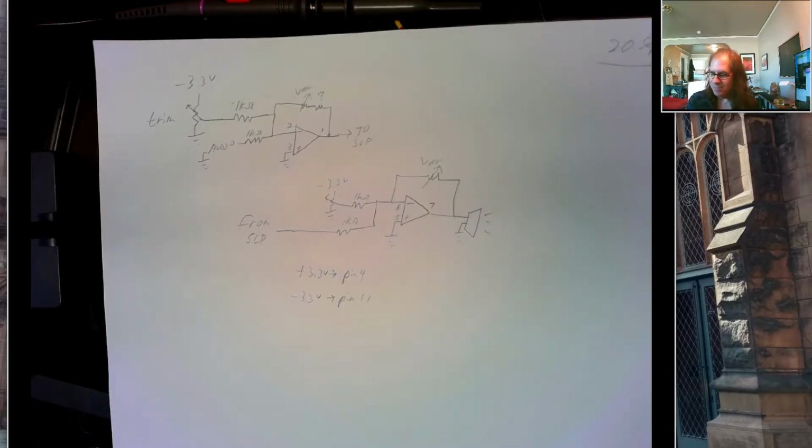So I'm playing around with audio input to the Songline processor, and audio input is an alternating signal, right? And it's usually centered around zero, so it goes positive and negative, and it's also very small. And the Songline processor expects analog inputs that range between 0 volts and 1 volts. So what I need to do is take an audio signal that's wiggling up and down around 0, and I need to shift it up so that it wiggles between say 0 and some positive voltage, and then I need to amplify it because right now it's going from 0 to about 0.1 volts, and I'd like to have it go from 0 to 1 volts.